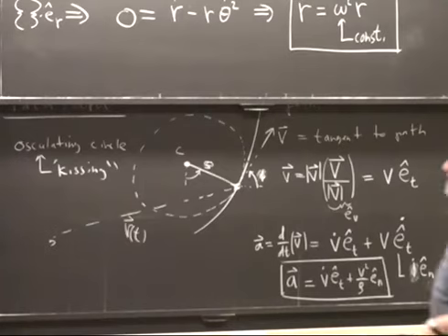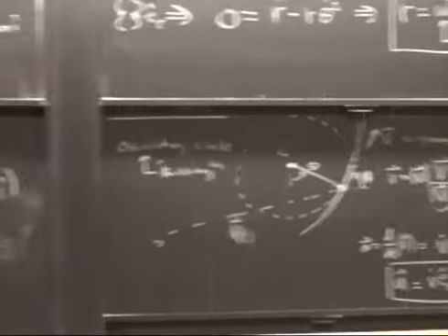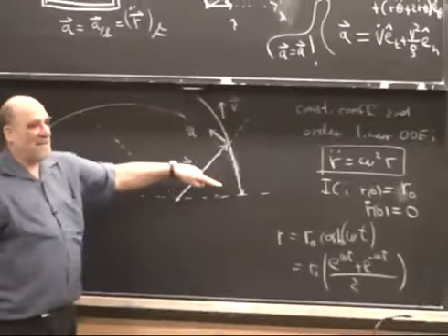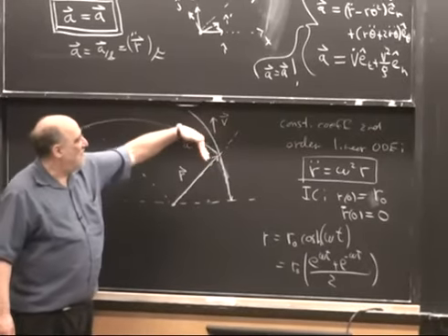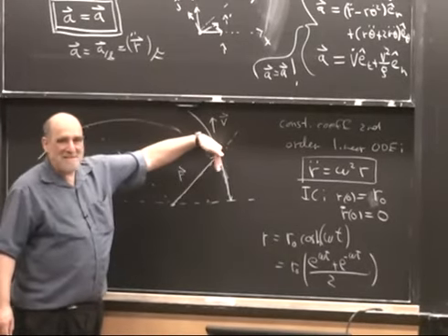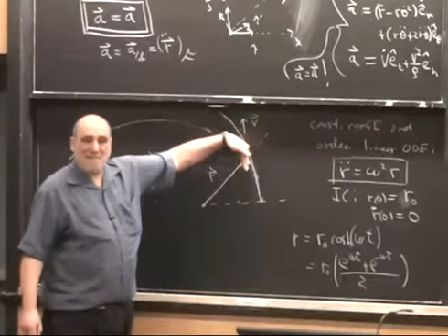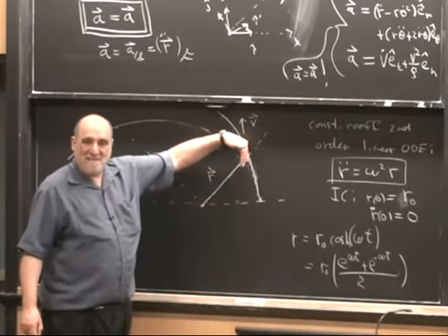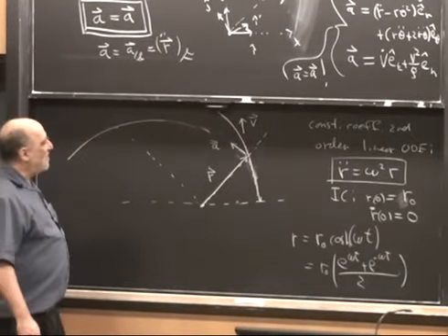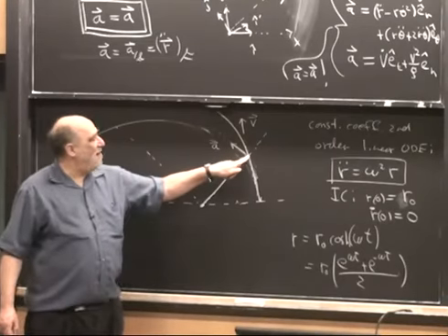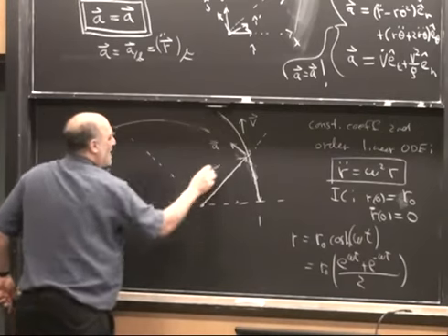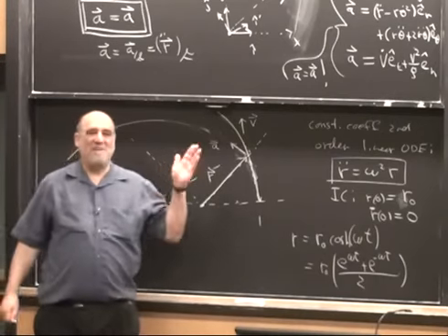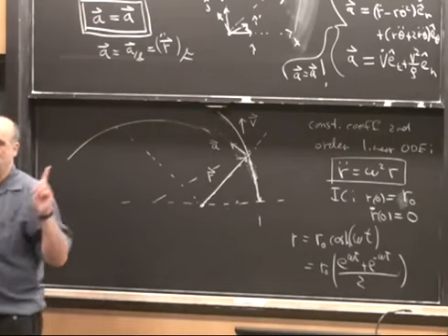That is, even when we had this crazy path over here, which was an exponential spiral, at every instant in the path, we could draw a circle which doesn't just touch the path, it's not just tangent to the path, but it's intimate with the path, it's kissing the path, it's second order tangent with the path, and that circle is like this, and this particle, relative to that osculating circle, has an acceleration towards the center of the circle, which is v squared over rho, and an acceleration tangent to the circle.